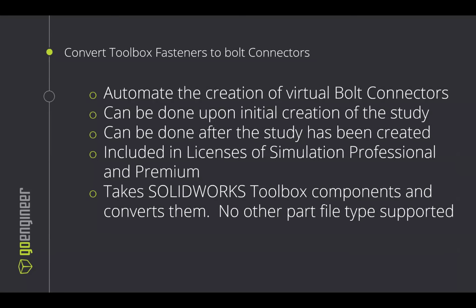All right. The next tool or utility is a way to automate the creation of virtual bolt connectors or fasteners in simulation. So this can be done on the fly. If you're already inside of a simulation study, you can activate this capability. Or if you're starting fresh, doing a new simulation on the initial creation, there's a little checkbox I'll show you. And this will take Toolbox fasteners.